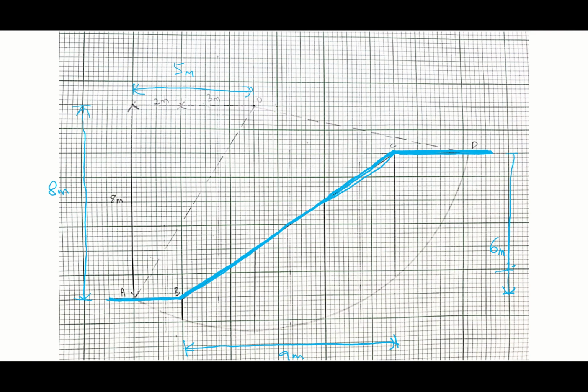Okay, next is to produce the slip failure plane, and that is the semicircle drawn on the piece of paper. So I just read from your workbook how to solve everything, the step-by-step guideline from your workbook. Okay, the first thing is to determine the value of the radius of the circle, R. So you have the horizontal line here, which is 5 meter, and then you have a vertical line here about 5 meter.